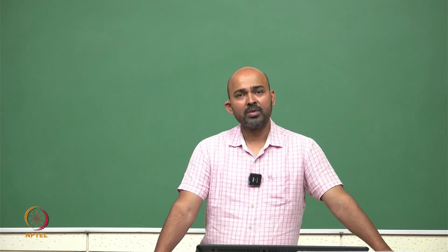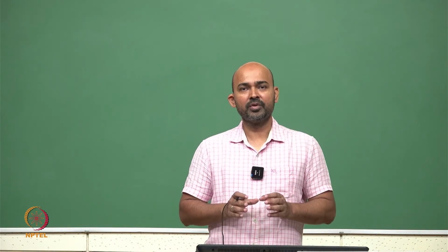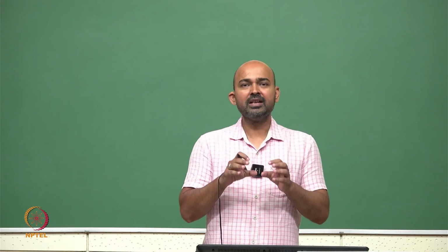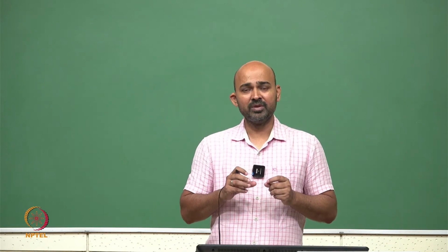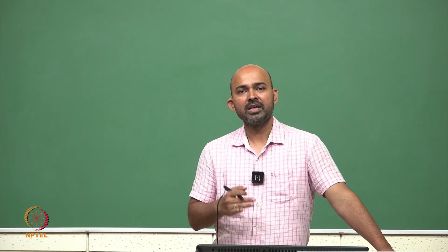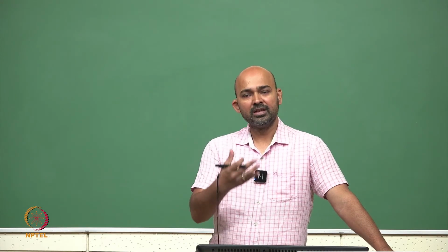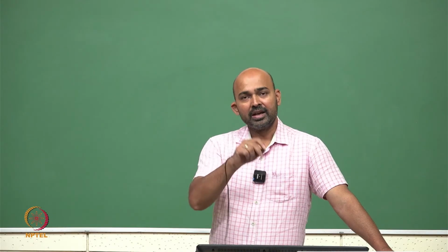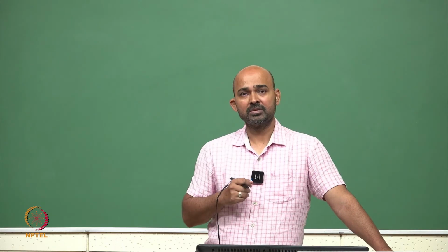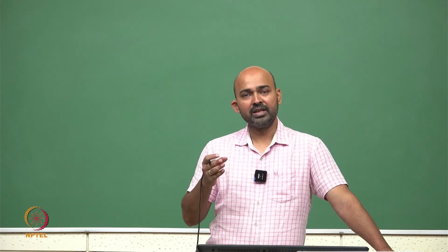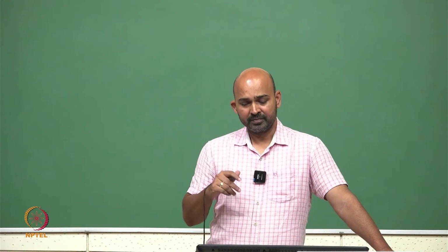Last lecture we discussed the schematic design where we use KiCad software and create a schematic using some symbols, a very small schematic, and we saw various steps. How do we take the symbol from a library, put it together in the schematic sheet, connect them together using a wire, then we need a ground plane and the supply plane. We saw that we can label a net by the net label command.